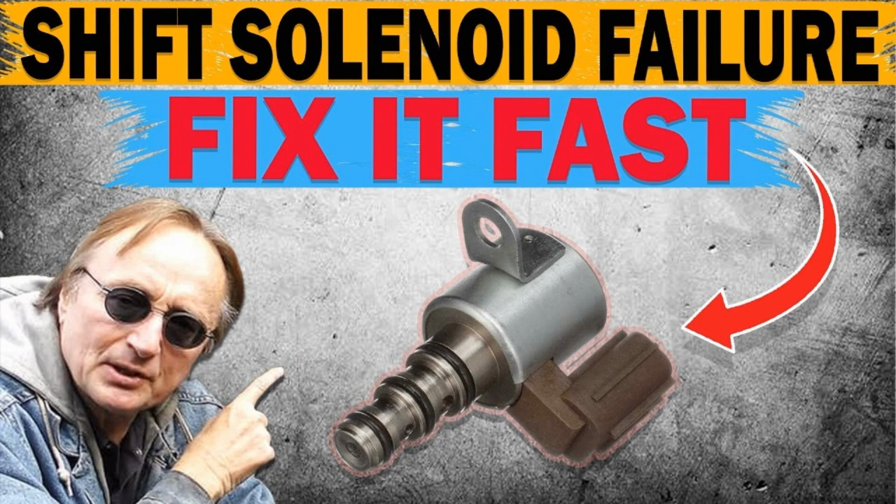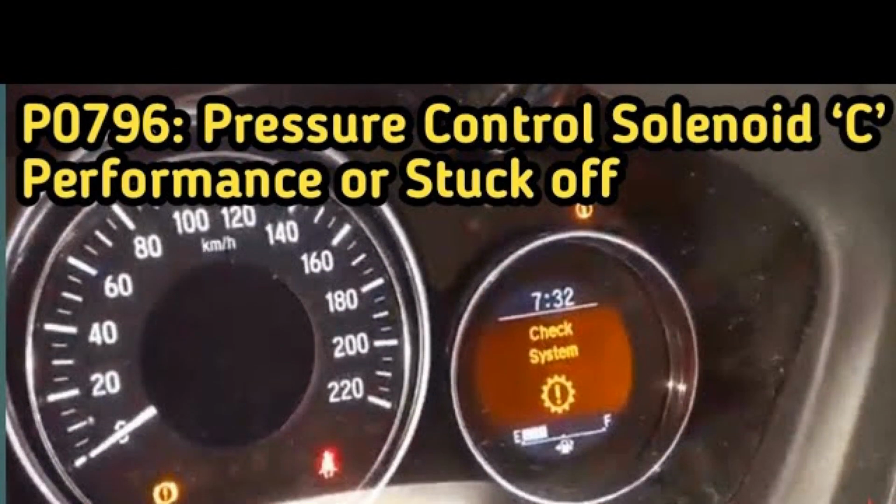The car enters emergency mode. The gearbox slips during gear changes. The transmission is stuck in gear. Gear changes are difficult. Transmission overheating. Increased fuel consumption. Possible symptoms similar to those of a misfire. The P0796 fault severity is generally moderate, but can quickly rise to a more serious level if not corrected in time.